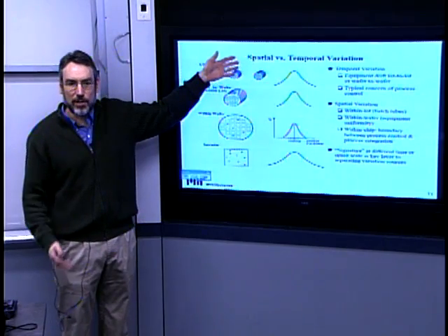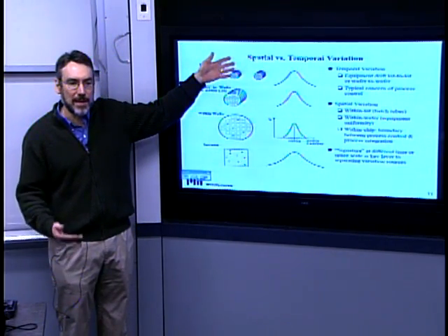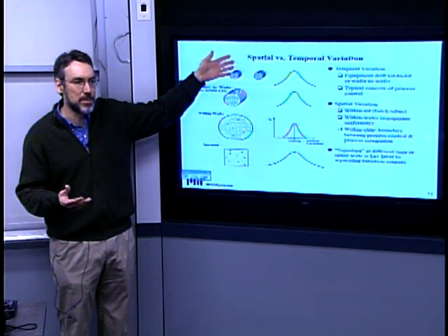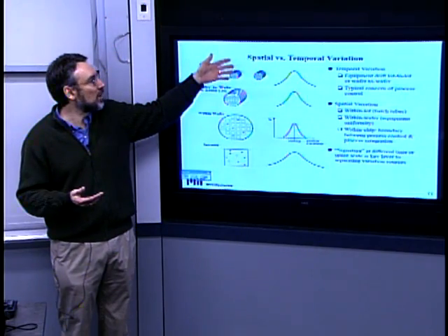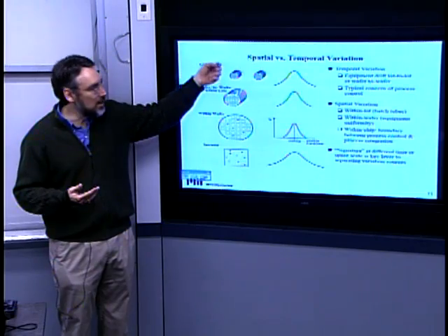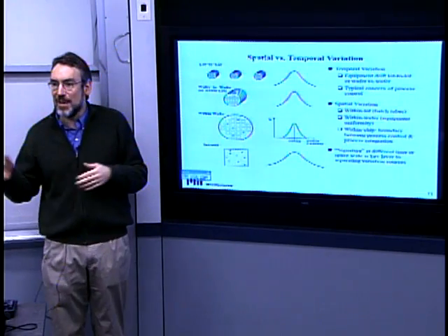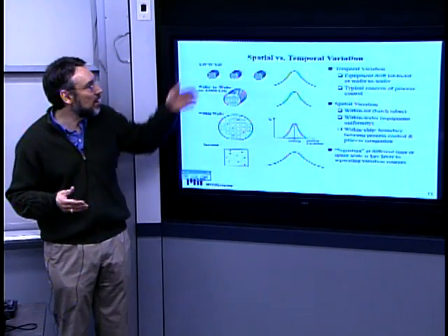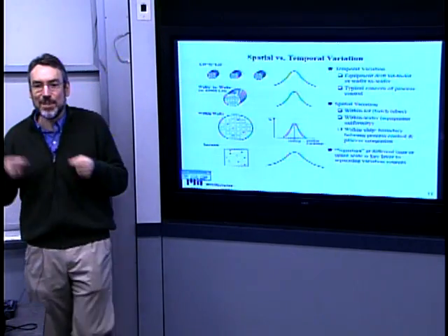Some companies, and there's not a lot of them these days, have multiple fabs. So I could continue this up. Intel in particular is very famous for making the same product in multiple fabs in multiple states and in fact multiple countries around the world, and they work very, very hard to have matching from one fab to the other in terms of the equipment and so on to minimize fab to fab deviations or differences in their chips.